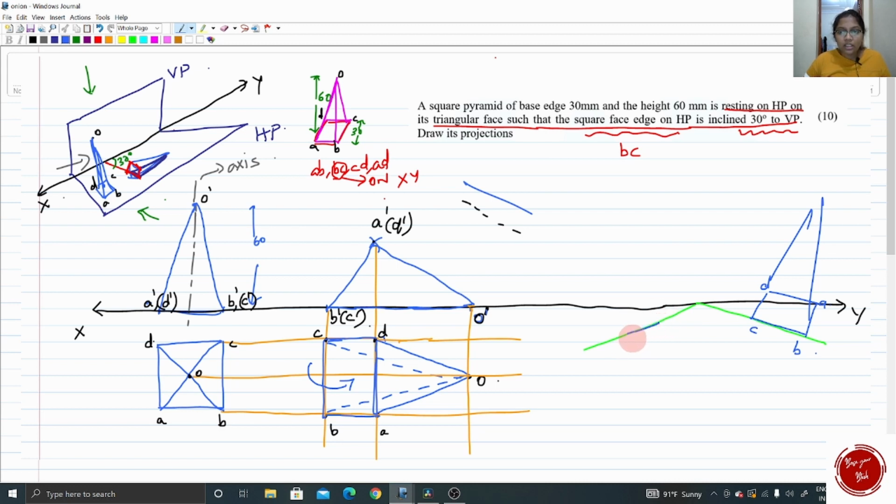Okay, so start drawing the CB edge over here. Just take 30 degree towards left and take any random point and mark C, and with this length mark B, and draw a perpendicular from B and take this length to get your A value, and draw parallel to BC from A and get the point D and close this.